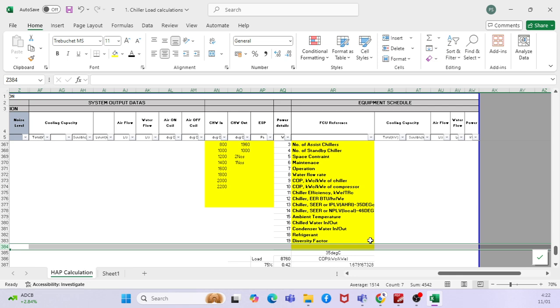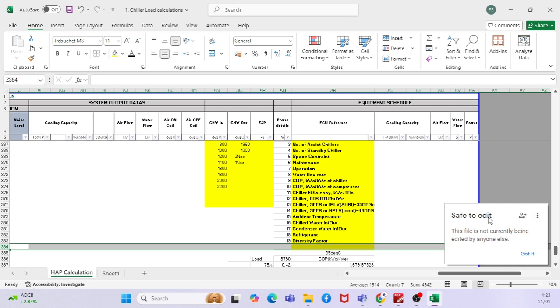You understand, right? Can you repeat it once again if you don't mind? What I'm saying is, when you go to a higher elevation, you may require a higher airflow rate to cool the chiller heat, or you may have to go for derating. Clear, right? Because of the height increasing, your density is decreasing, right?